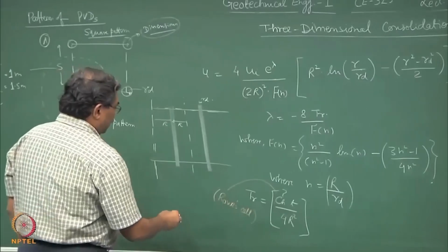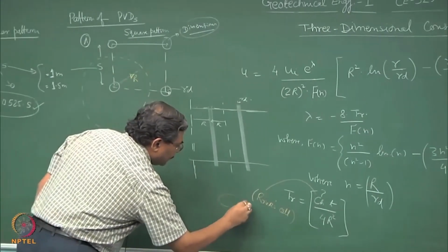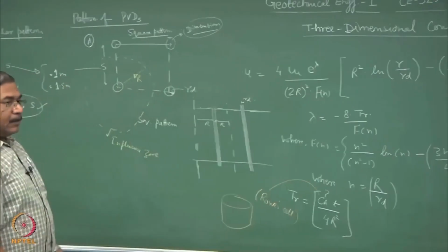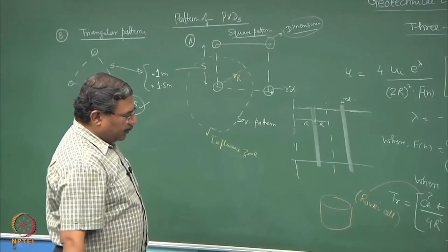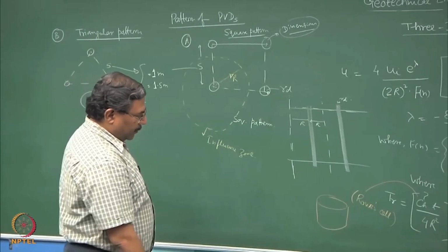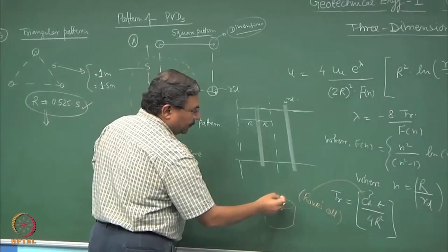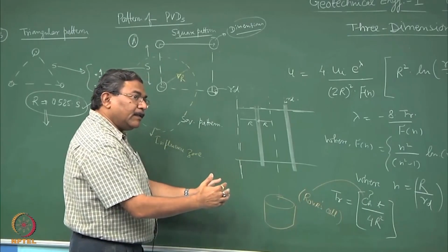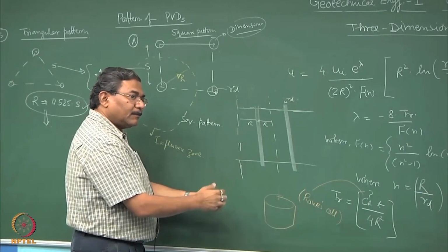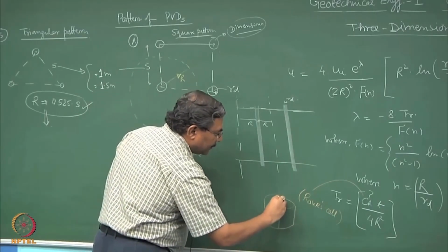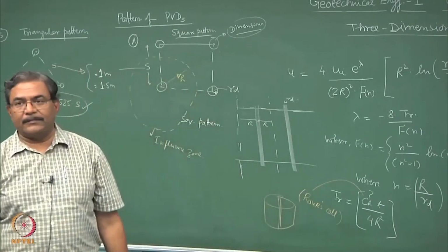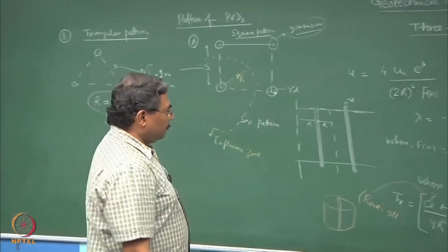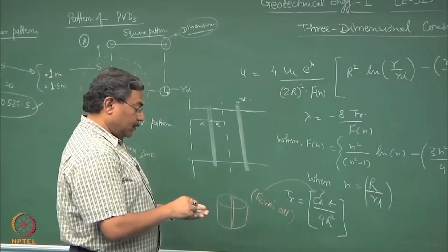What it does is, there is a sample which is maintained in a ring or a container which is cylindrical, and rather than applying the vertical load, there is a mechanism by which I can squeeze the entire sample radially in, and the drainage is applied at the center path. Expensive device, but this is the only way. Or the second way would be,